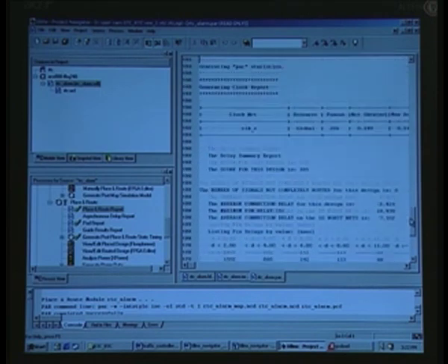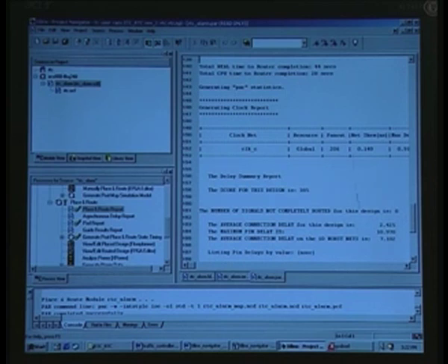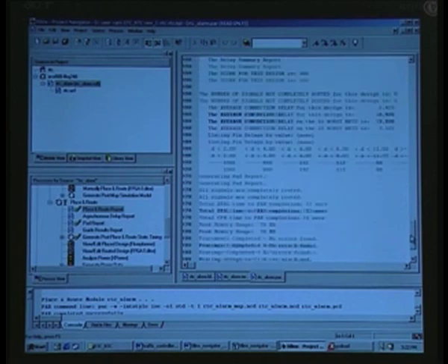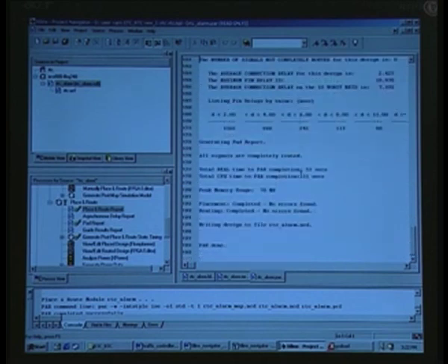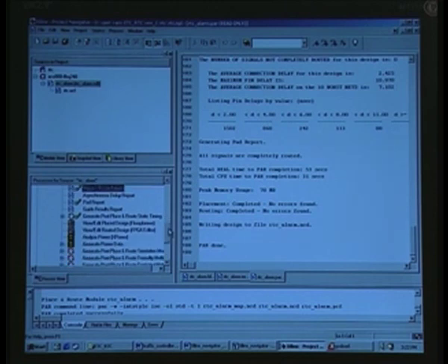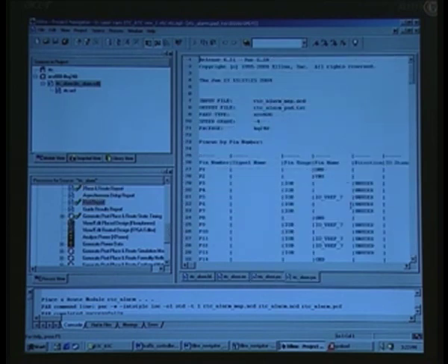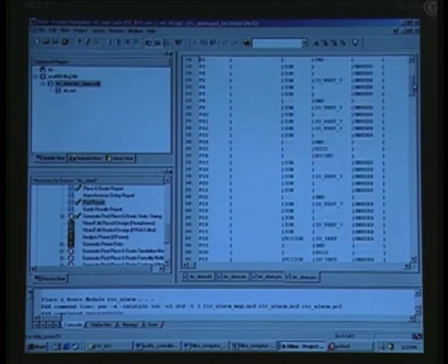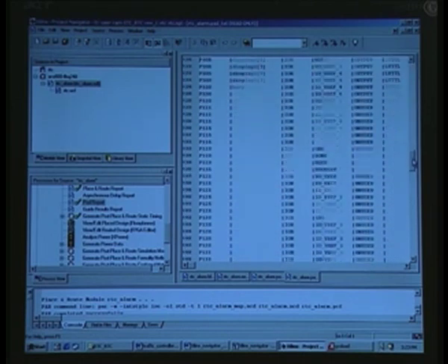And it also gives the timing summary here. Let us not go into the details right now. When we come to that design, we will see this, basically the timing details, and finally it says place and route there are no errors, and that is what is here. And next, we have seen implementation, then mapping, then place and route, and you also have a pad report separately, and that will list all the IO pins that have been connected, and that is what you see here on the right.